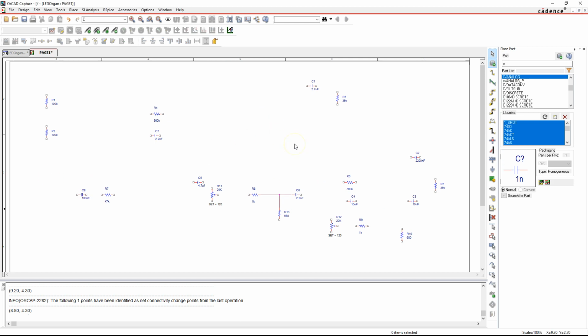The last sets of things we'd want for the main part of the schematic is the MC33071 chip /ON, and that's at the ON op-amp library. So hit enter on your keyboard and then place it right around here-ish. And there's that. Where else do we want to place this? Well, actually, that's the only instance of this operational amplifier. So I'm going to hit escape.